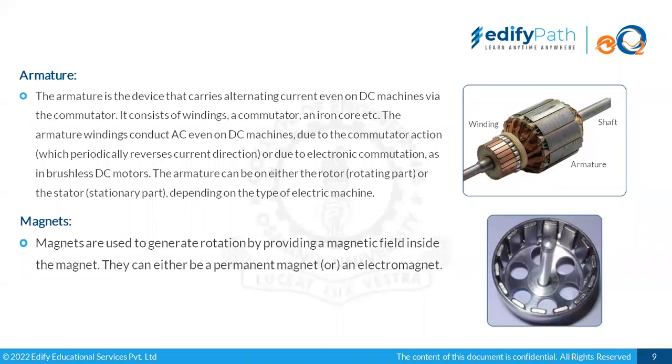And for electric vehicles, we spoke about how we need a powerful motor in a small space. For that, the permanent magnets also have to be very strong. So we normally use rare earth magnets, which are very powerful with very high power density. That helps us make a very powerful motor in very little space.